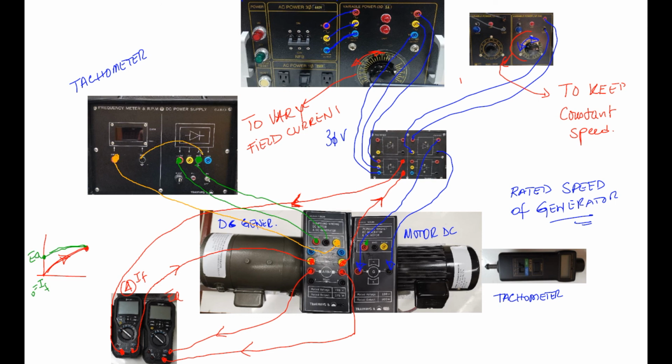You can ground it directly from here. So jumper from ground to ground. So now we supplied our tachometer via the generator itself, and we're reading those, what you call sensors, inside this generator. So here we'll be displaying the speed of our system, of our generator.